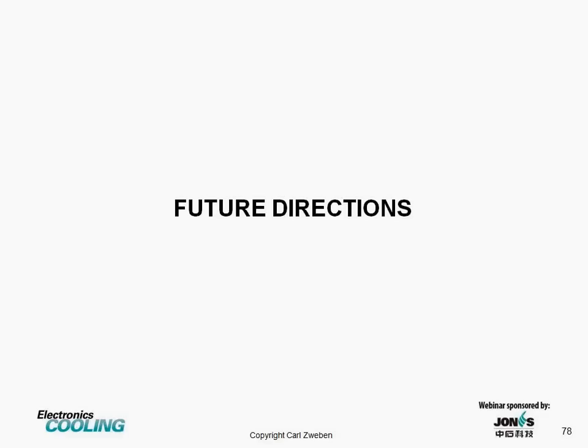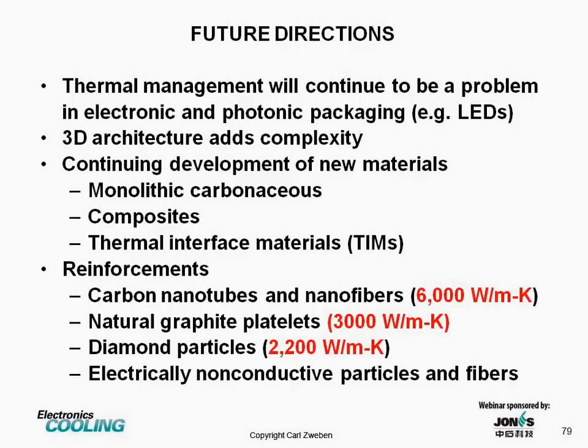Next, we'll take a look at getting out our crystal ball and trying to predict where things are going in the future. I think it's fair to say, without much fear of contradiction, that thermal management will continue to be a problem both in electronics and photonic packaging such as LEDs. The trend towards 3D architecture adds complexity to the thermal management problem. As a result, I anticipate continuing development of new materials, monolithic carbonaceous, as we've seen, composites, and new thermal interface materials incorporating many of these carbon-based materials.